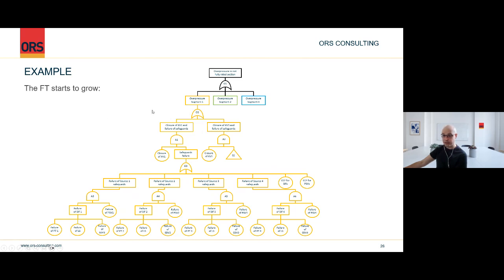The easy thing of this is that it's a lot of initiating events that you know the frequency for, and you know, for example, a failure of a PSV, how many times per demand that happens. So this is a frequency. This is probabilities of failure on demand, right? So these are probabilities, these are frequencies, and then you multiply them and you get frequency plus frequency, and then frequency plus frequency plus frequency, and then you have the frequency of the total event, and you know your acceptable risk target, right? So the only variable you have to play with is these 3 failures, right?